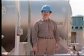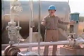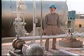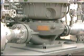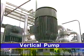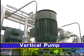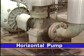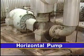Pump design features normally considered in classifying pumps include shaft position, bearing position, type of impeller, number of impellers, volute design, and fluid flow. You'll hear the terms vertical and horizontal when centrifugal pumps are talked about. The terms refer to the position of the shaft during the pump's normal operation. Shafts in vertical pumps are perpendicular to the ground. The driver is usually positioned above the pump. Shafts are parallel to the ground in horizontal pumps. The driver is usually positioned beside the pump.